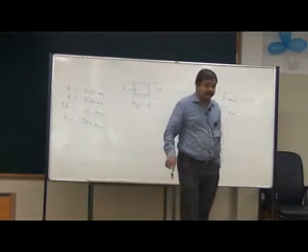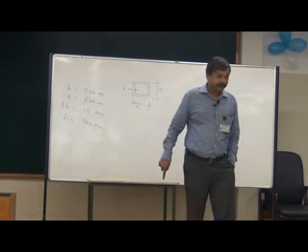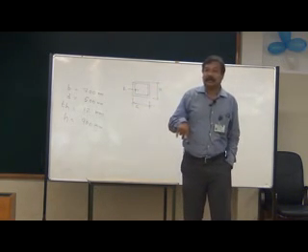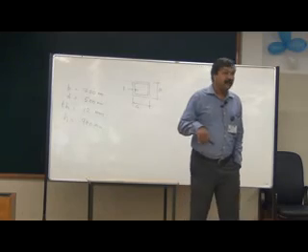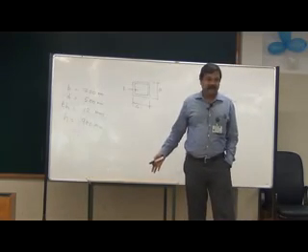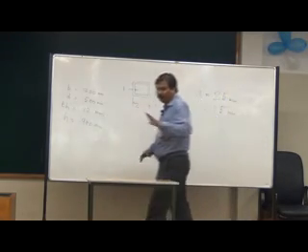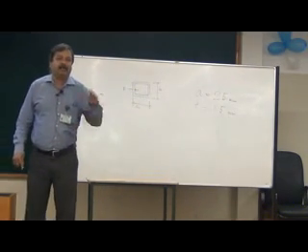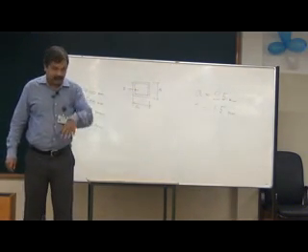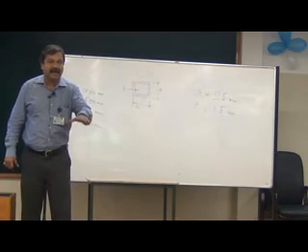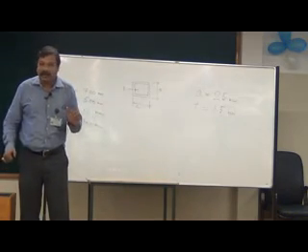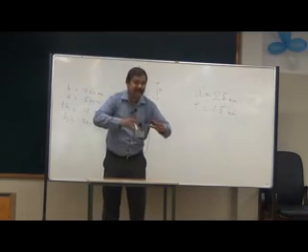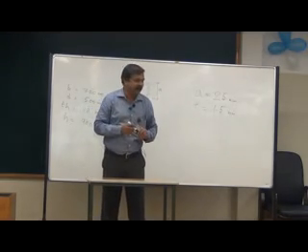Right. How did you arrive at this height? 900 mm. Why not 1000? Why not 600? Height of the chair. Okay. So the sitting part of the chair will be about 600 mm from the ground. When somebody sits in a chair, he should be able to comfortably rest his hand on the table.